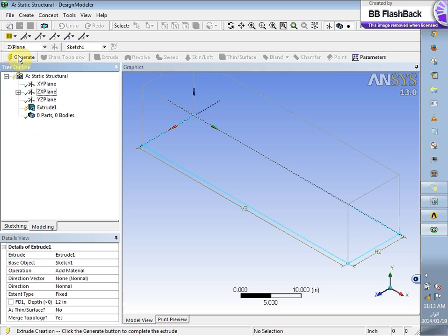It's not completed yet. Also, you can see red is not there. This means some step needs to be done yet, which is the extrude creation. And what you can see here is it has made this gray box outside, which it has extruded upward. And here it is telling us the depth, how deep the extrusion should be. It is 12 inches. We planned it to be 1 inch thick. If I write -2 here and click outside somewhere, sorry, it cannot take the negative. You can change the direction afterwards. Let's say 1 inch here now.